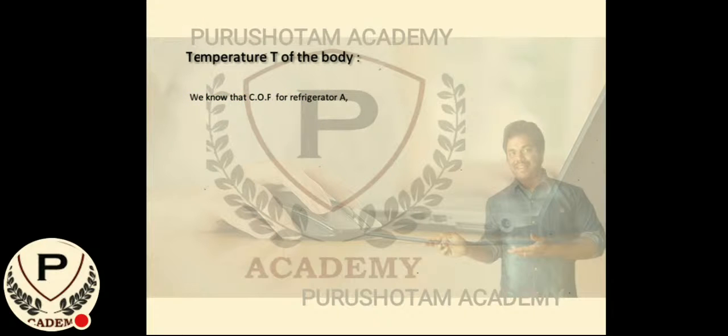So we know that the COP for refrigerator A, COP equal to T1 by T2 minus T1, that equal to 300 by T minus 300, and let us assume this as equation 1. And COP of B equal to T2 by T3 minus T2, where we don't know the value of T. Okay, and we know the value of T3, so we will substitute the values, that equal to T by 1000 minus T, and let us assume this as equation 2.